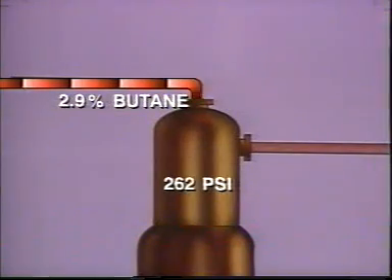Suppose we increase the system operating pressure without adjusting any other variables. The increased pressure causes less vaporization to occur, so less butane will enter the top product. The overhead product becomes lighter and less of it is produced. We get the same effect as we would by decreasing the column temperature. Normally, we try to maintain the column pressure as low as possible within the design limits because this reduces the amount of fuel needed to vaporize the feed components.